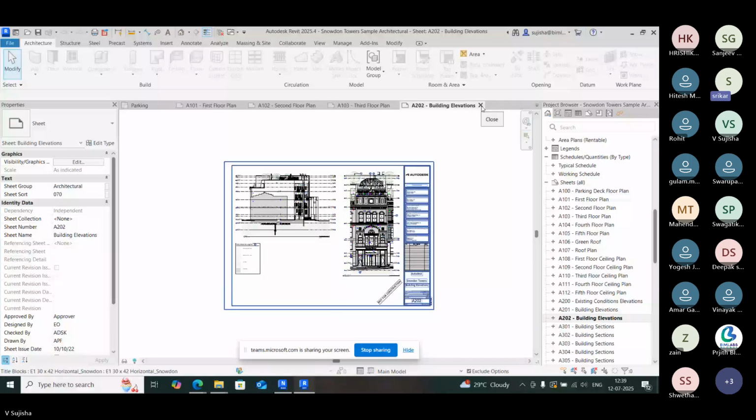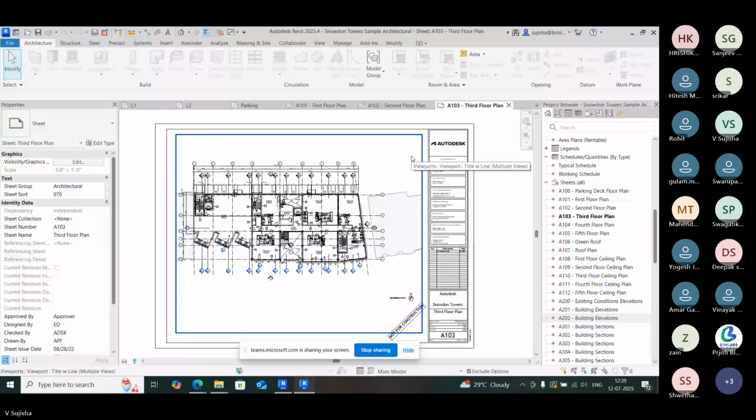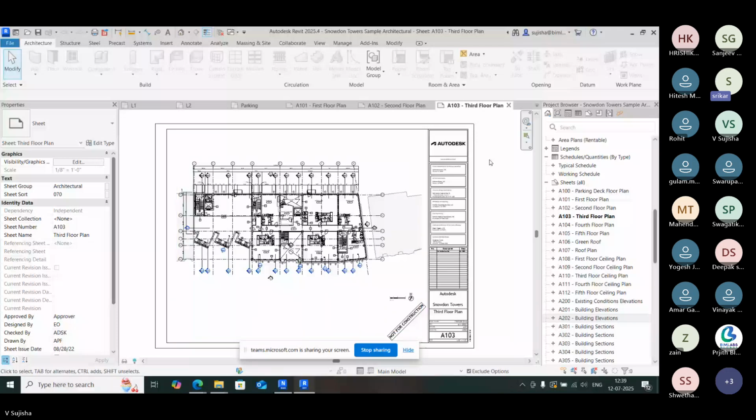Ma'am, is there an augmented reality or virtual reality integration to this in the BIM software? You can use augmented reality. From this, you can export the file and use it. Okay, will that be .obj or something like that? Will it retain all the details? You need to export it as .ifc, and if you export it as a .ifc file, it will maintain all the details. Okay.